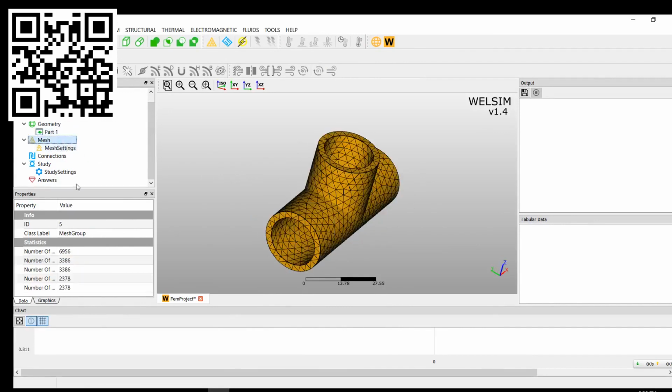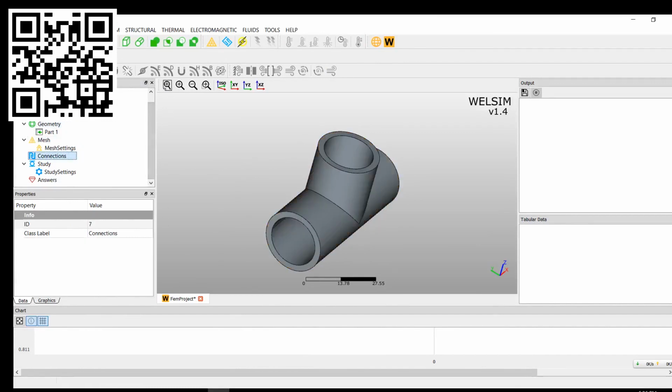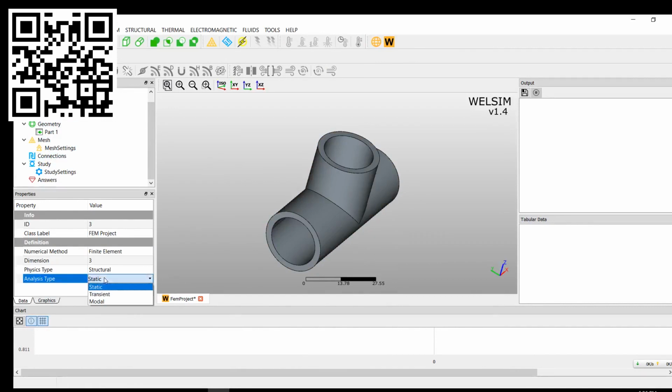Okay, pretty fast. Now we have 1010 elements generated. It's about 7,000 nodes here. Okay, then don't forget, since we'll do the transient structure analysis today, we change the static to the transient in analysis property. When we change to transient, we see another property showing up. It's called time integration, and the default value is implicit. Basically, you can change it to explicit, but for this case, it's not a very high-speed simulation, so we use implicit. It's good.